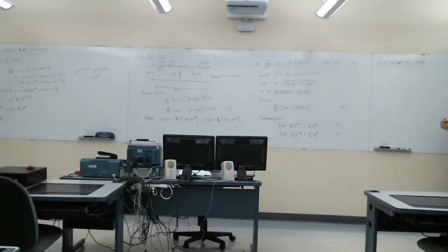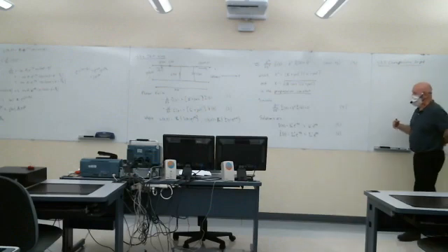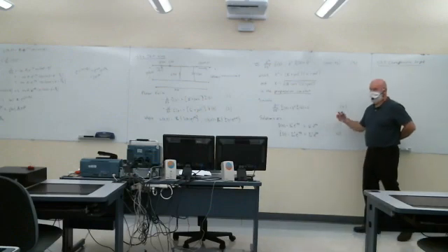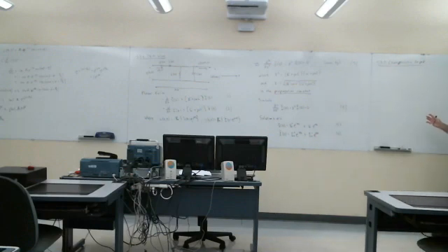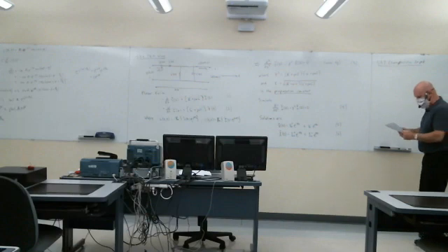Or when we're working with phasors, the ratio of V to I is called impedance. So we have that here on our transmission lines. There's a constant ratio between the V phasor and I phasor on our line, for the waves propagating in each of the directions. That's called the characteristic impedance of the line.